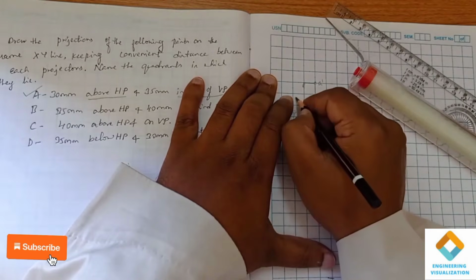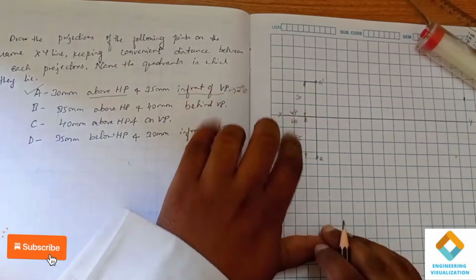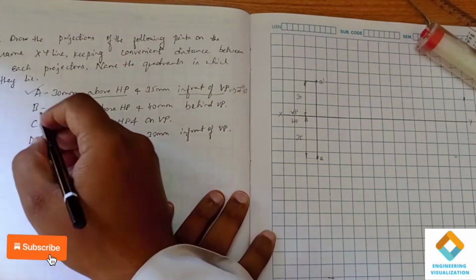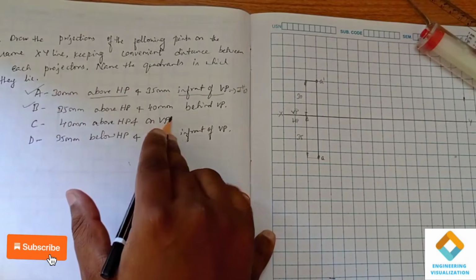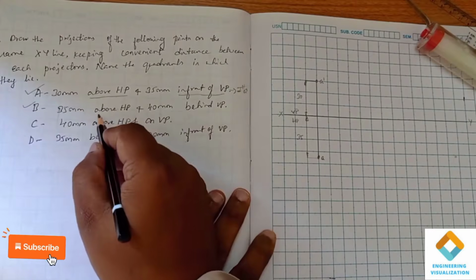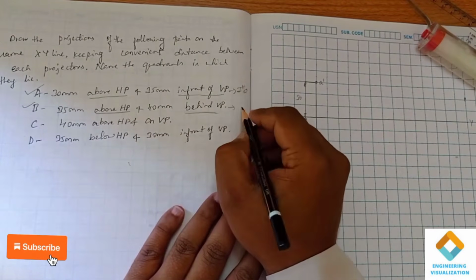So this is 30 and this is 35. Now we are done with point A. Similarly we look at point B: 35 mm above HP and 40 mm behind VP. So above HP and behind VP means it is in the second quadrant.